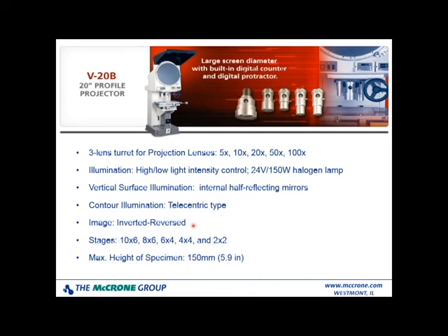This one is the V20. This is a 20-inch profile projector. Again, the screen is 20 inches in diameter. It has a turret with 3 objectives; 5x, 10x, 20x, 50x, and 100x objectives are available. And this is a floor standing instrument.